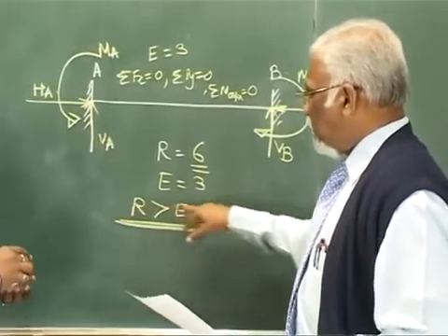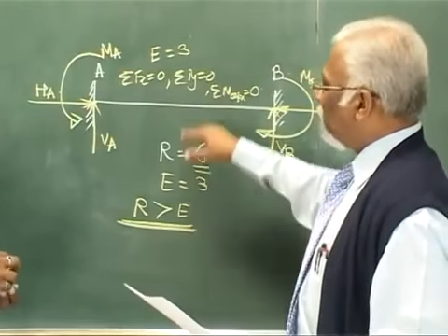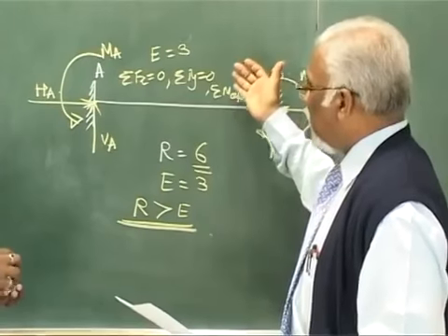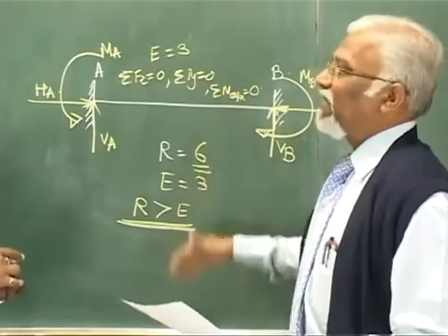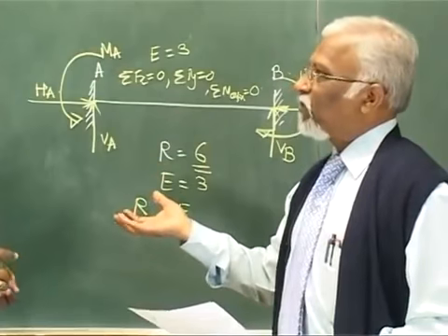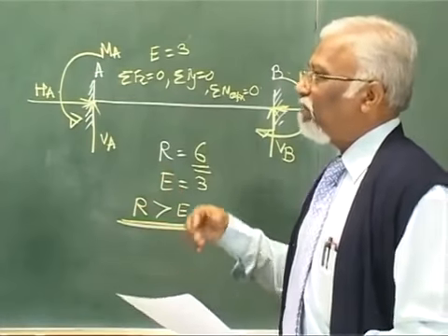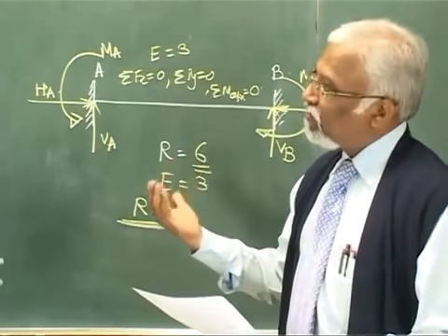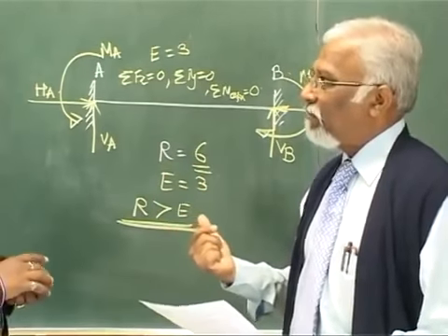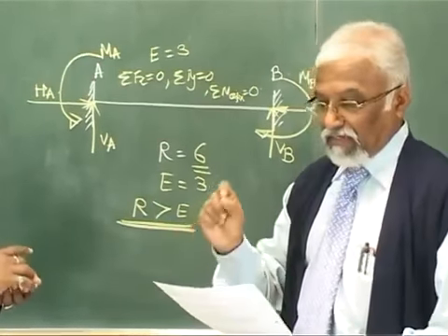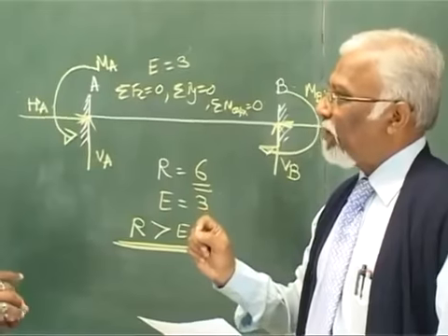So as R is greater than 3, it means that whatever equations are necessary to solve, the reactions are much more. Yes, sir. So automatically you are not able to solve these particular problems. Yes, sir. So you are saying that it is a statically indeterminate beam.